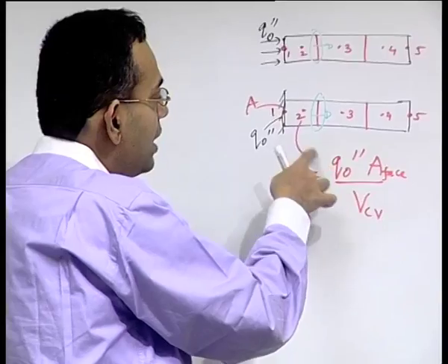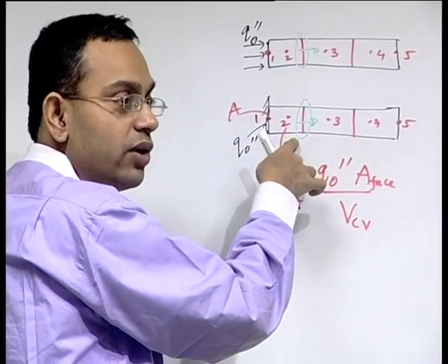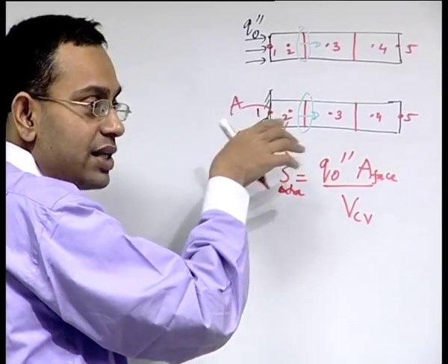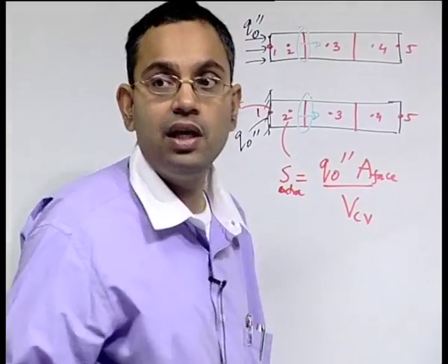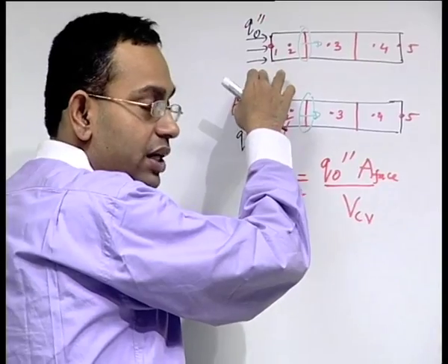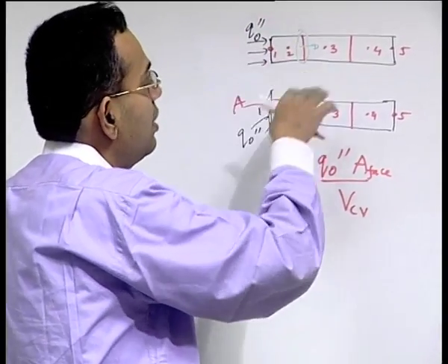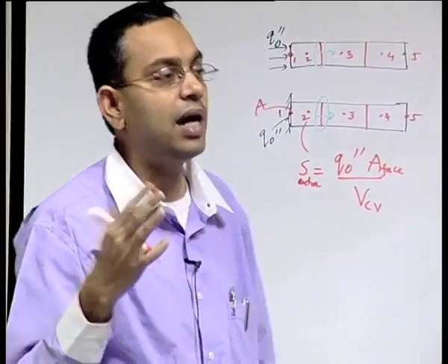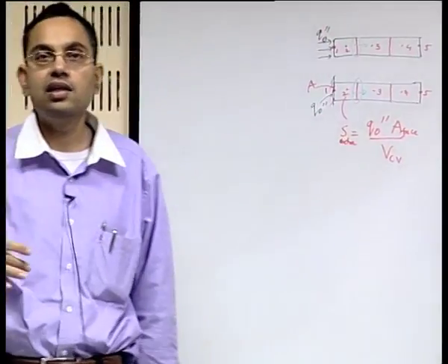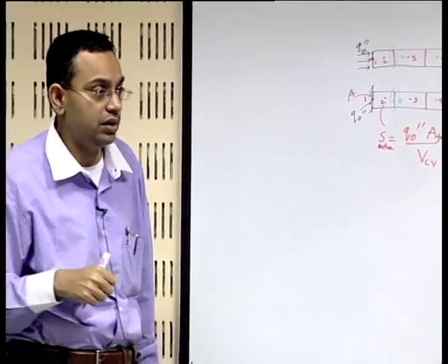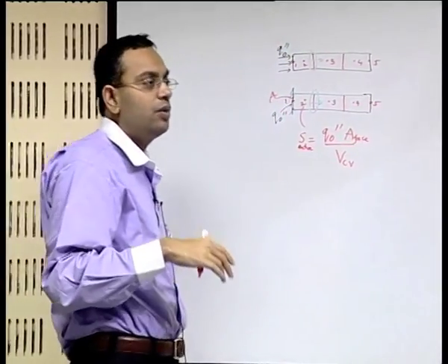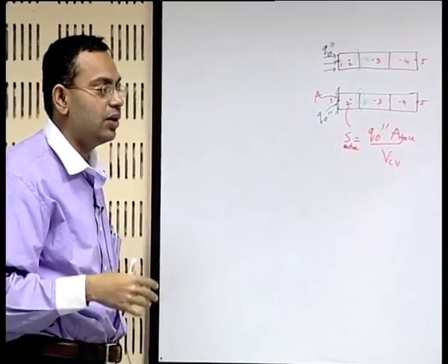Here you have made the effect penetrative inside the control volume in one shot by making it a source term, and that makes it converge faster in many cases as compared to the direct implementation of the boundary term. Of course, in many cases the difference is marginal, but in some very extensive simulations this difference may be of some importance. So, this is one trick in implementation of the heat flux boundary condition.